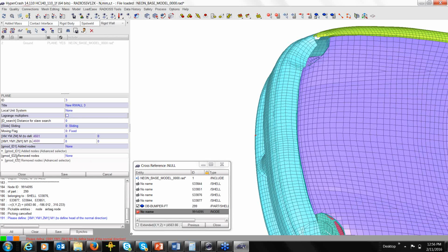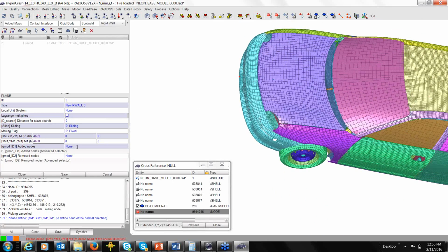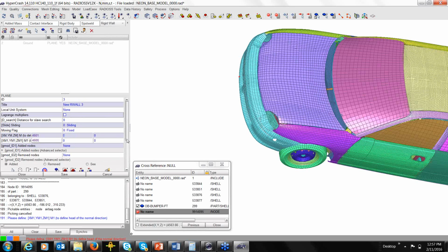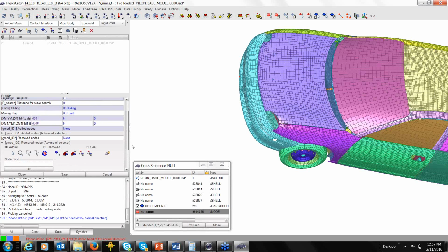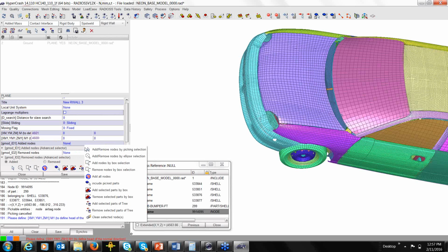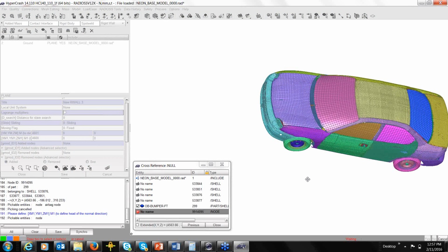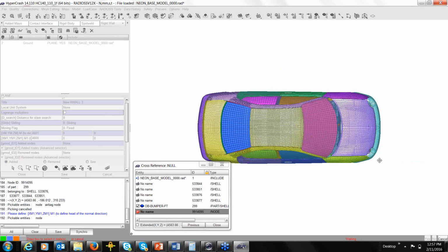And then when I create the wall, I need to create the, I say, group of node. I can select the group of node, or I can also put the distance, the search distance, and then I can put a group of nodes. So let's say I go select my group of node. I go here, set the group of node, I mouse click, and I say I want to select this node. Put it right here, and I pick up these.